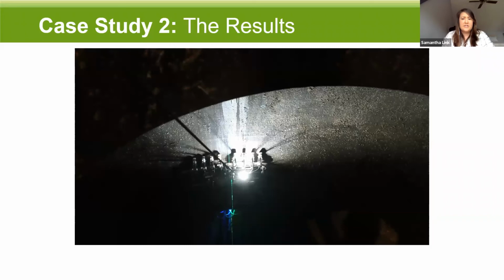Great. And how does a digester inspection differ from a storage tank inspection? A digester inspection is very similar in a lot of ways to a storage tank inspection. The biggest differences would be the construction and the materials. Typically we're not seeing storage tanks that have Inconel weld overlay on the inside, so storage tank inspections tend to be maybe even a little more straightforward than a digester inspection. But there are a lot of similarities. Running the shell of a digester versus the shell of a storage tank is very similar. And then in a pipe, how does the robot handle deposits?